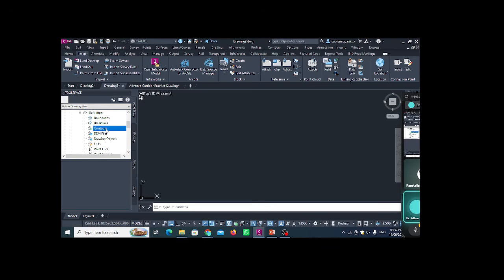देखिए, सिविल 3D में हर काम करने का बहुत सारा स्टाइल है। सेम काम करने के लिए 10 चीजें मिलेंगी, लेकिन दसों चीजों को लेके हम काम नहीं कर सकते। तो अगर हमारा मेन पर्पज सरफेस क्रिएट करना है, तो आप उसका CSV फाइल बना के इंपोर्ट करो, या गूगल अर्थ से एग्जैक्ट लोकेशन लेके इंपोर्ट करो, या सीधा उस फाइल में कंटूर बनाओ।